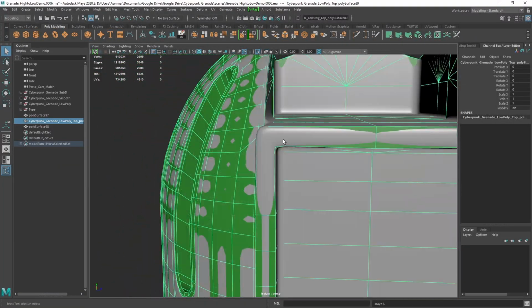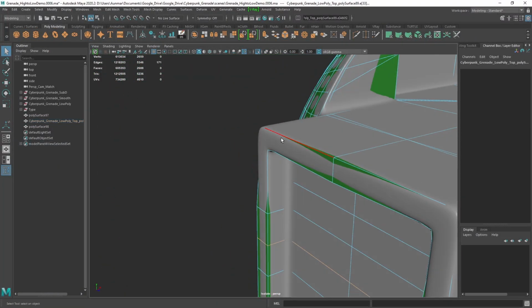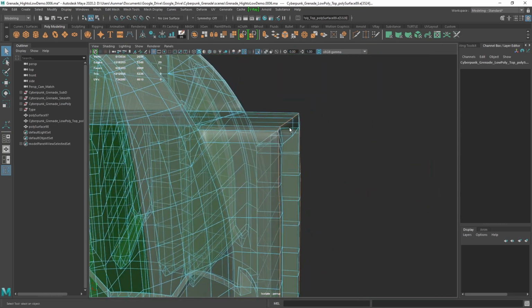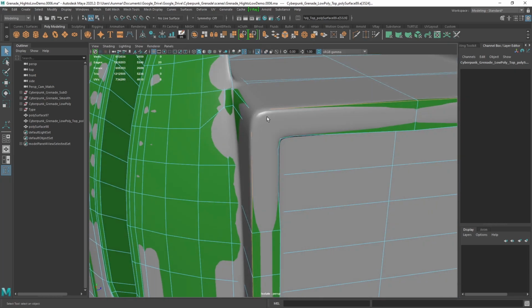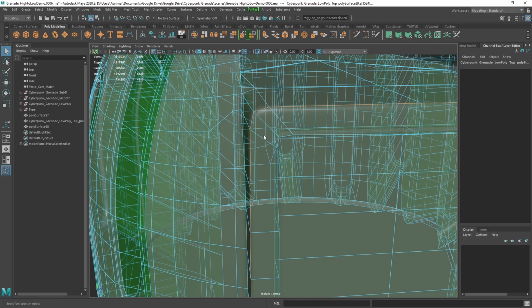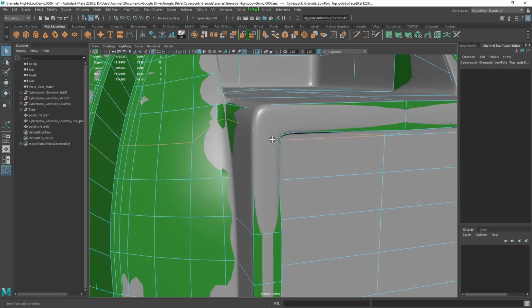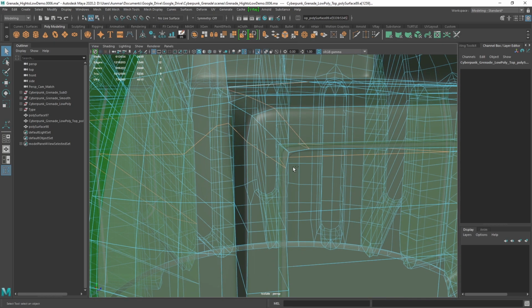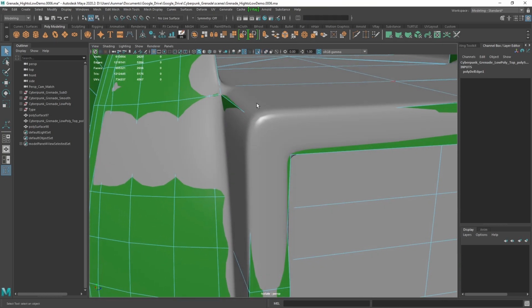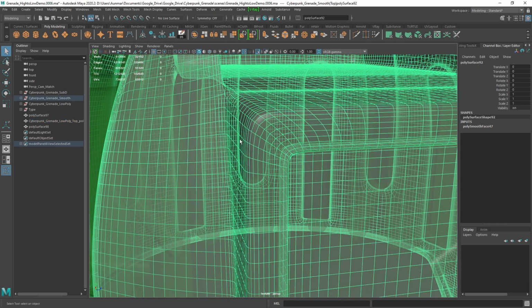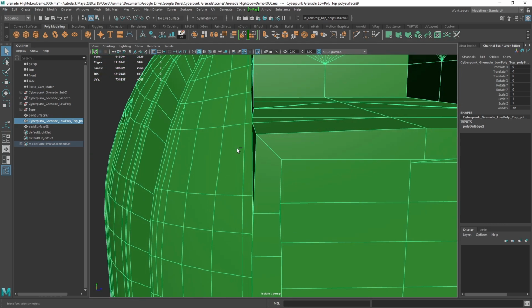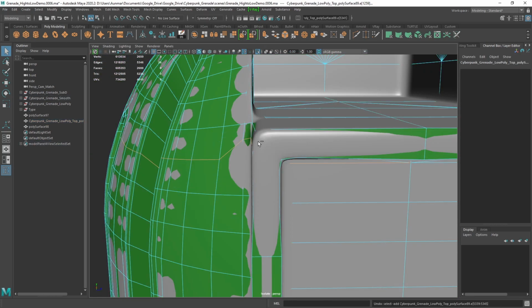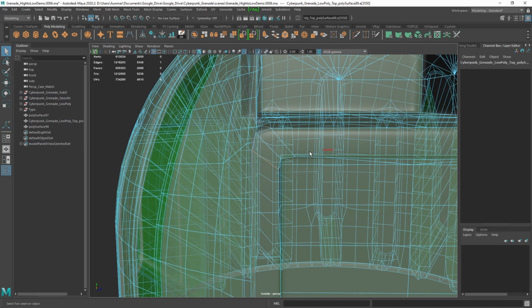In some instances, it's okay to have these kind of corners here that are completely flat. But if you have corners like these that have a nice round radius, having a very sharp corner... I'm going to just quickly delete this and then I'll undo it. If I remove that, trying to bake this round corner into this is going to produce a lot of artifacts. So that's why I want to make sure to have a good radius for our corners.